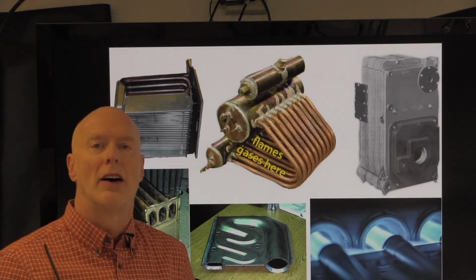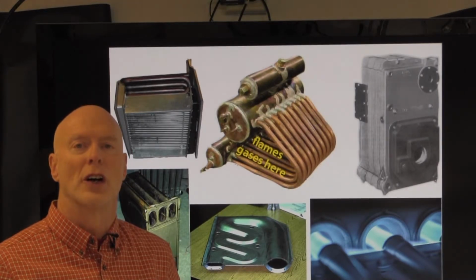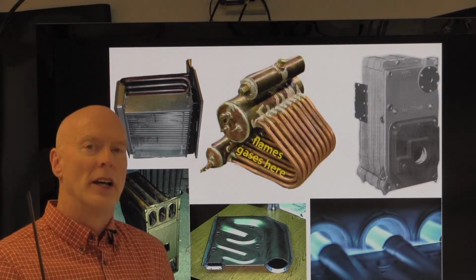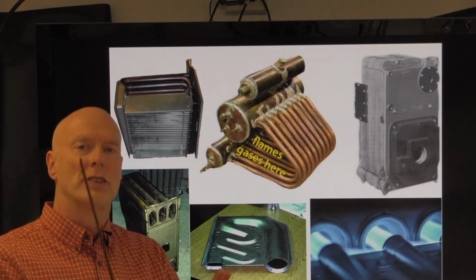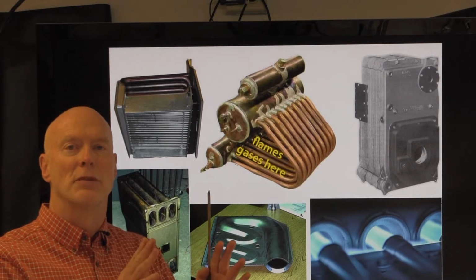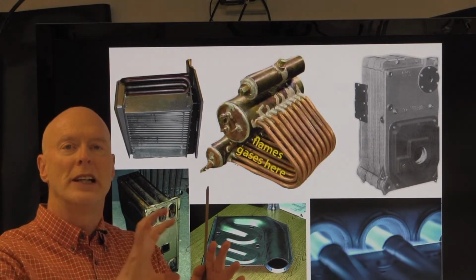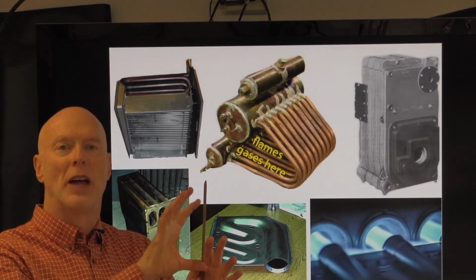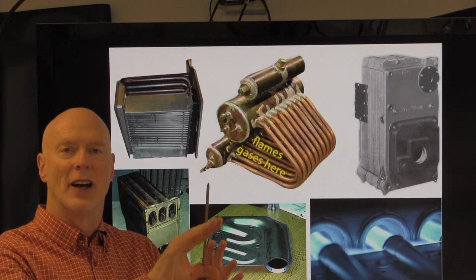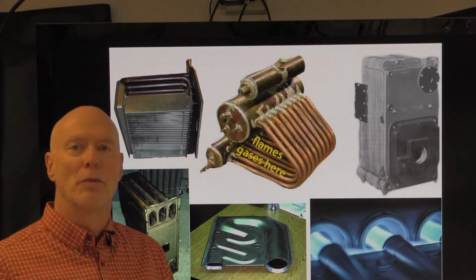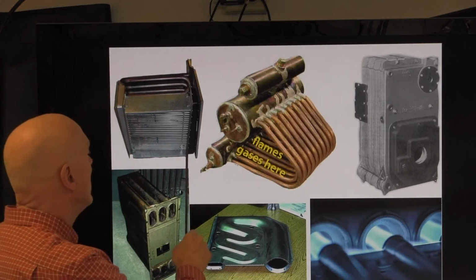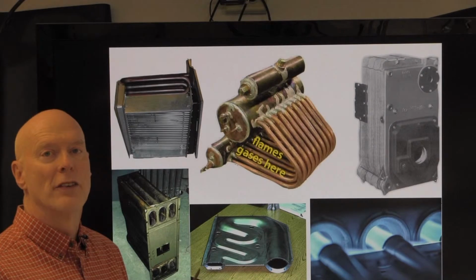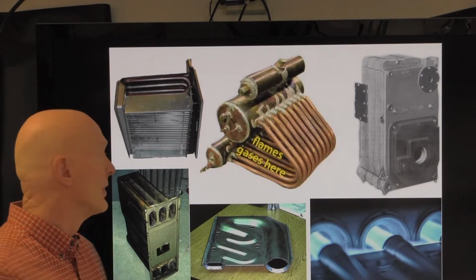The reason why we want condensation to occur in a heat exchanger, and especially in a stainless steel heat exchanger, is because if we have the products of gas combustion and we leave the water vapor in there that was formed by the combustion process, we're wasting like 12% of the heat at least. This heat exchanger is designed to condense the water vapor out of the flue gases.